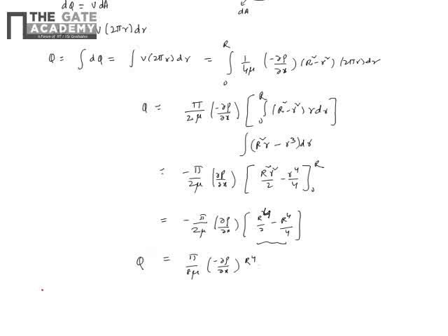And how I define, now these are two important concepts. V mean is basically the total flow rate divided by the total area of cross section. When I take Q by pi capital R square, the total area of cross section, I get pi by 8 mu into minus dou p by dou x, and because this is r power 4, when I divide by pi r square, I get minus dou p by dou x into 1 by 8 mu into r square.